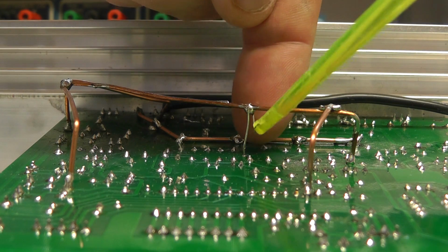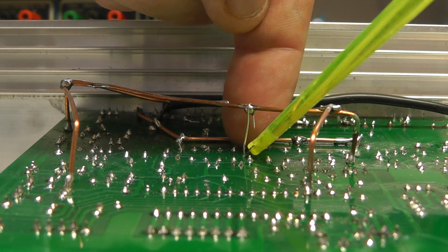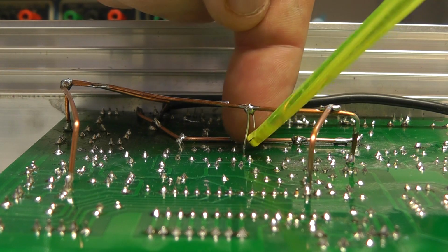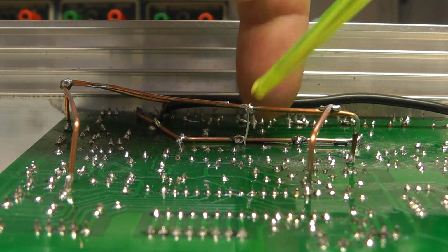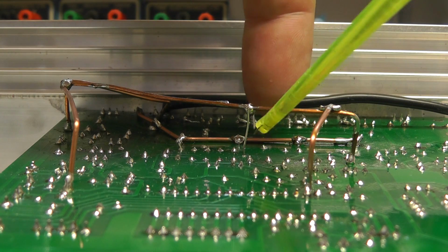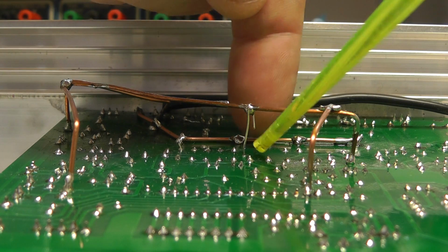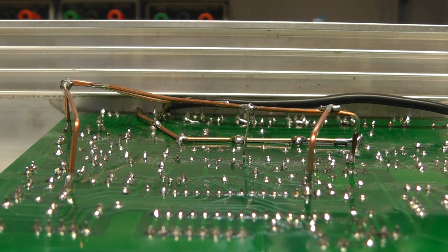It's actually soldered at either side of the PCB, so that goes through a little slot on the board, which is already there. It's a little test point, and it's a through hole, so we just put that straight through and solder from both sides. I'll show you the position of that when we have a look at the other side of the PCB.